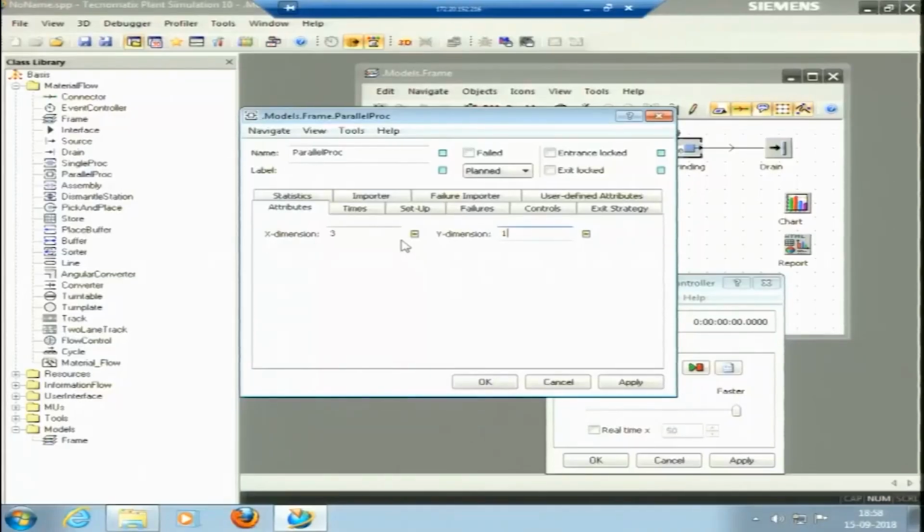Now, when there is waiting, when there is blocking, we can think of adding new machines, or taking a few machines off, and if there is a lot of waiting time, sometimes we can even think of doing some other processes, like I have said in case of the process layout. In a process layout, we have a specific set of machines in one section, another set of machines in another section. If we see the overall machine time, and in this specific section for 30% of the time there is a waiting, we can just consider that 30% of time and give them some other job. Okay, some other job could be given.